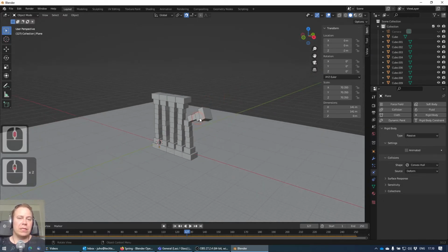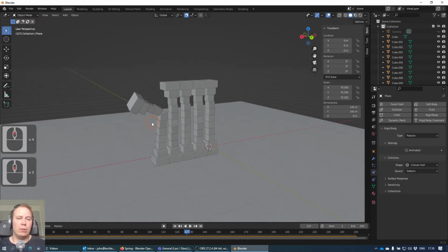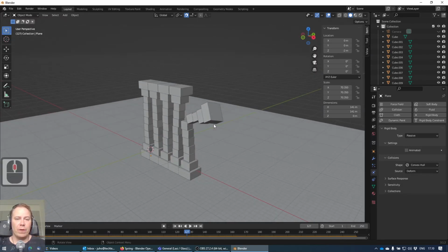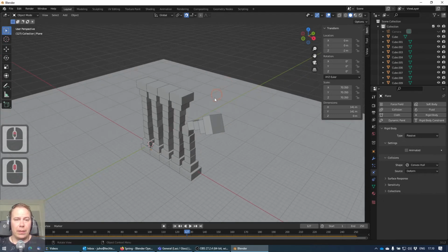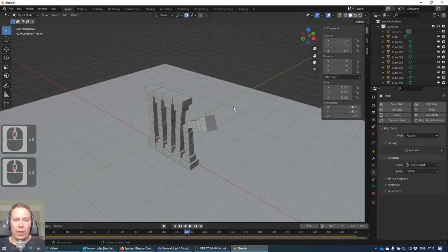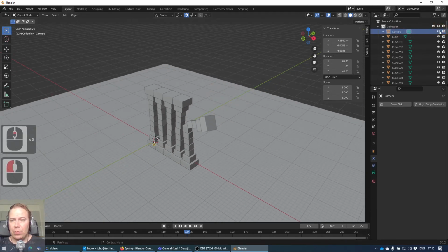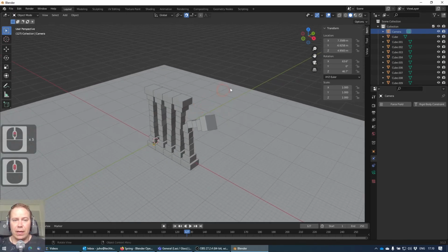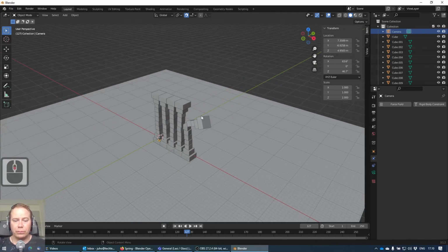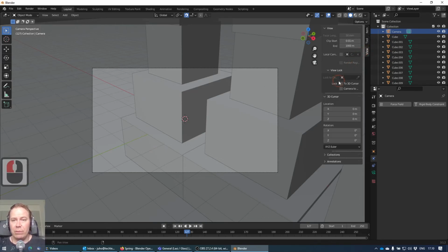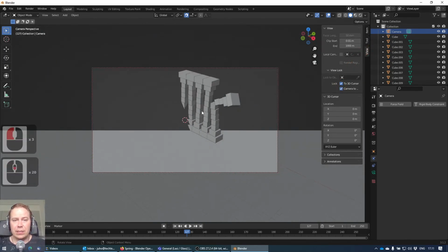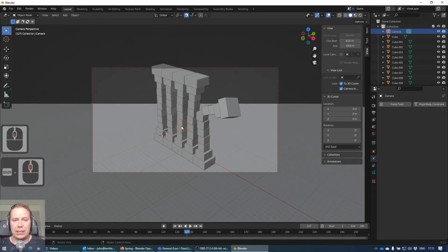Yep, that's it. That was a little bit extra, but you see what 3D is capable of. You can now render the image, for example, how you want it by clicking on F12. But you need to make sure that you have the camera there. Camera view is, by the way, 0, and if you want to move the camera, this is gonna be the next thing.